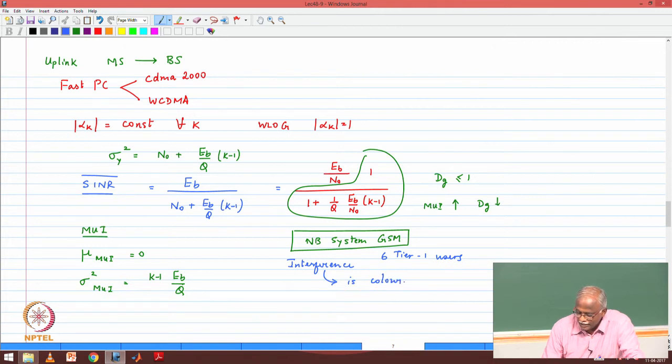It has a strong spectral shape which looks like the GSM signal. So, interference management in a GSM system has to keep in mind that once it becomes an interference dominated system, it moves away from AWGN, into a noise which looks highly colored. It has a strong spectral shape.